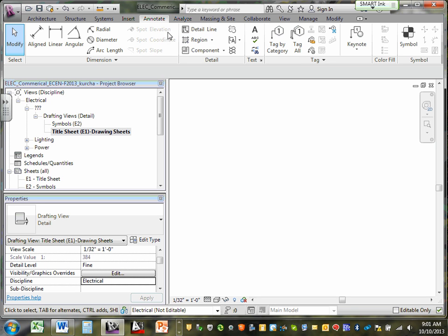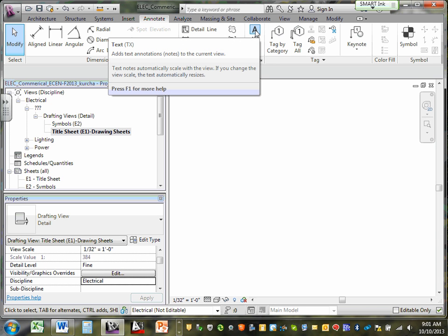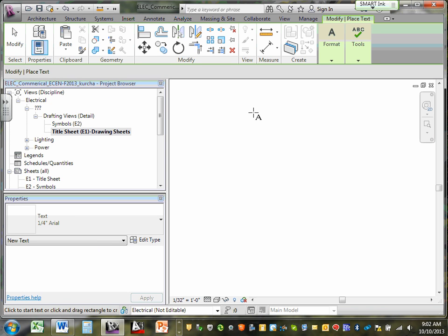Make sure you are in annotation. Click on annotation. Annotation and text. Did you guys get that? Annotation and text. Thumbs up, chat, so I can know when to move, when not. Okay, cool. All right, click on text. When you're holding a text in your hand, click and open a window as big as you want it to. Now you have a window to have a text, right?